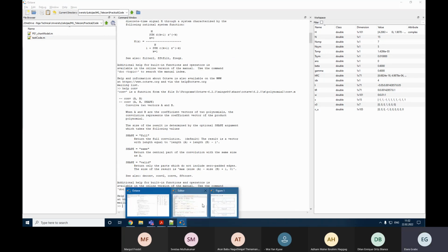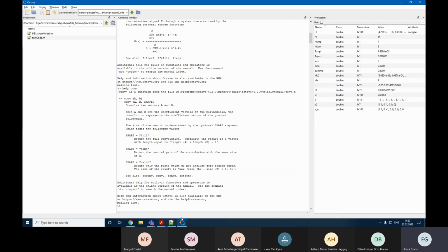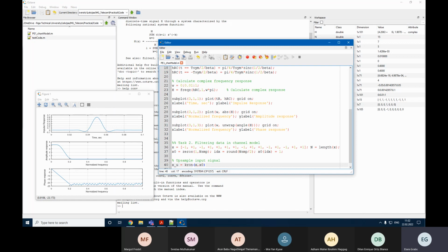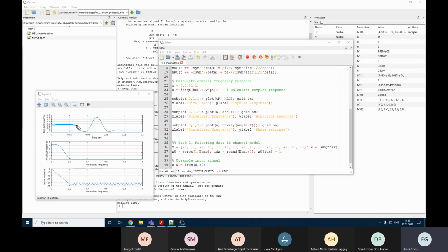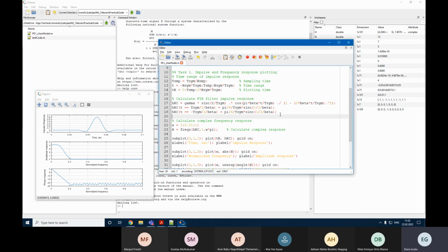Now, however, there is one practical thing, not really a problem, we need to consider when working with signals. In practice, it will take some time before we get to the first result. And this time for FIR filters with a symmetric impulse response is half of the impulse response length. So we need this delay value. I think I started talking about it in the last practical exercise lesson, which was an hour ago, but we didn't really get to that point.